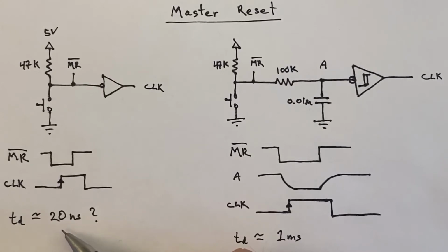However, the margin is only about 5 nanoseconds, which is a very short amount of time, to say the least, especially on our breadboard circuits right here, where we're just hooking things up with wires, instead of a precise PCB board. So this might work, but then it might not, and I don't know, it's a little close.